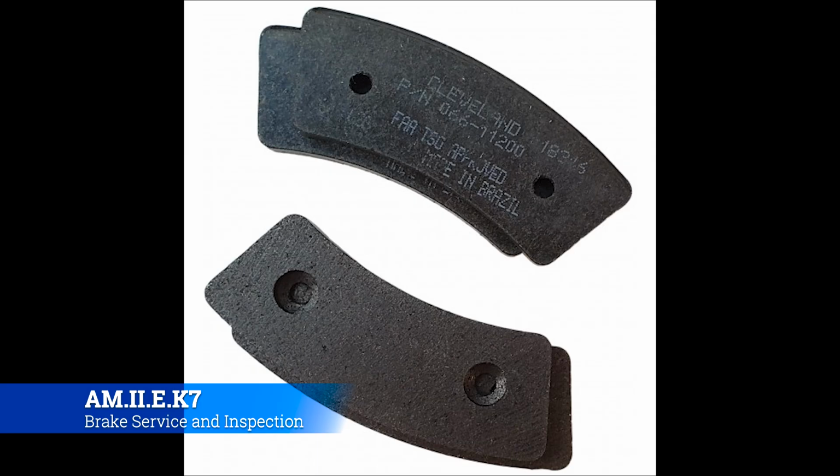Now, given that being the case, the aircraft manufacturer gives specifications for lining wear in its maintenance information. Meaning that every so often, either the brake pad has to be changed per, say, hours or calendar months, or on condition. Like on my plane, the brakes have to be serviced every 500 hours. Part of the brake service is changing out the pads, unless you do a check on the brakes during an annual and say, hey, look, the brake lining is not thick enough, and so now we need to change it.